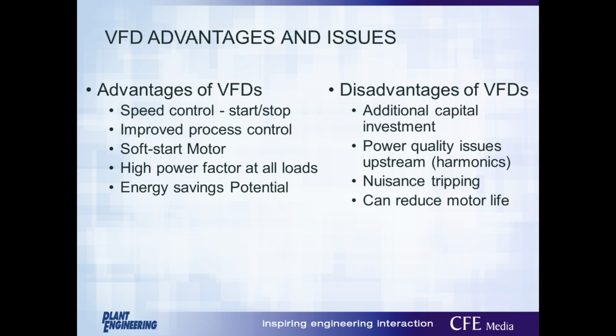What are the advantages of VFDs? Speed control. It's easy to start and stop the motor. No inrush current at the motor terminals, so less stress on the motor windings. Improved process control for precise applications, especially when you add encoder feedback in your VFD package. High-quality VFDs will have a high power factor at all motor loads, since the capacitors in the VFD are offsetting the inductance of the motor, and of course the energy savings potential.